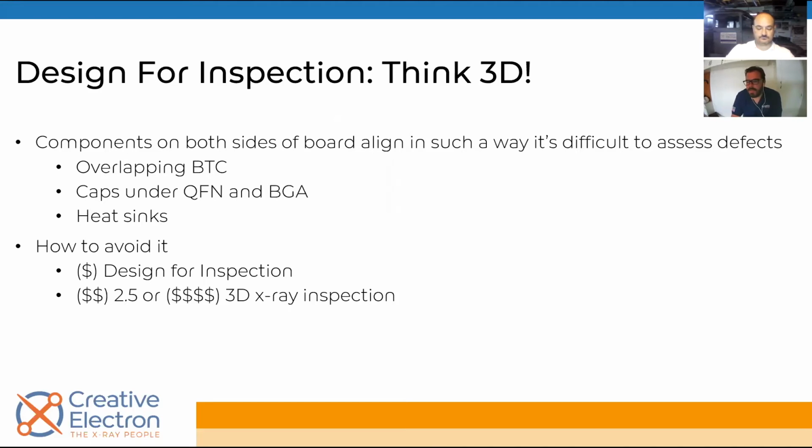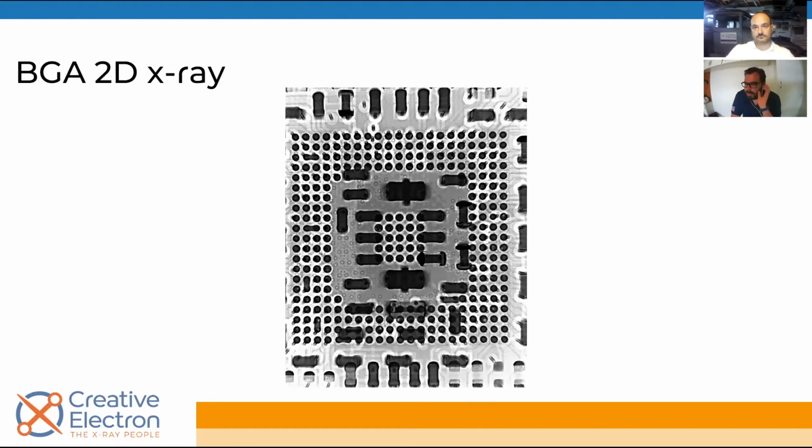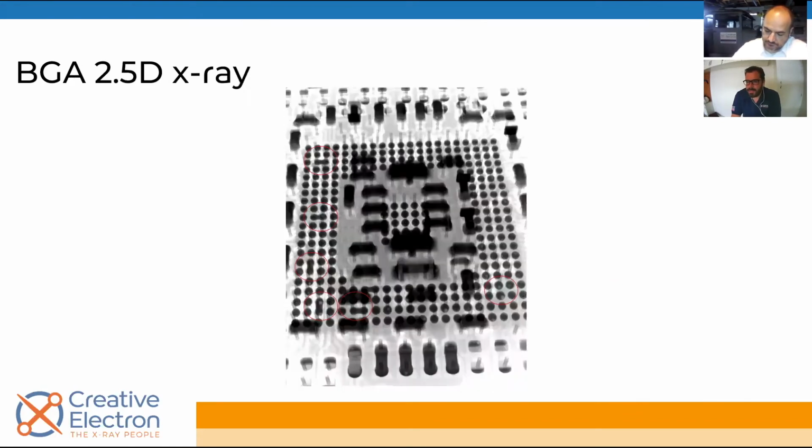Here we're going to go over some examples of complex devices. In this first example, we get a lot of capacitors on top of other devices. Capacitors tend to be very dense, so we can't see behind them and can't analyze what's happening there. If there's a whole ball missing, or a whole device missing behind a capacitor, you might not be able to tell.